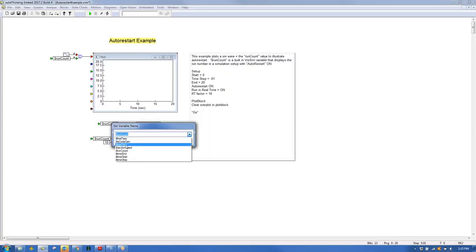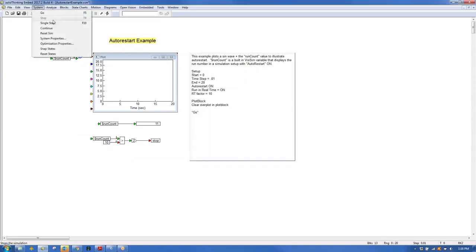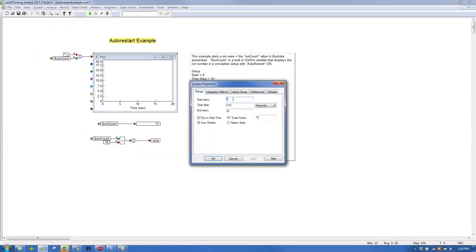Last pass is similar to first pass, except it flags the last pass of a simulation. Random seed just has to do with identifying the seed used for the random number generators if you find yourself using those. End time, start time, and step time are these parameters that I showed you under the properties menu right here, these 3 parameters, start, step, and end.